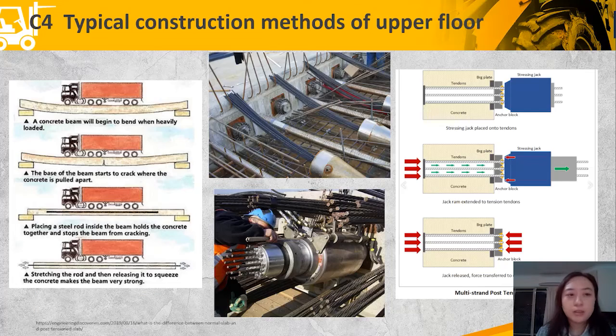When the concrete bears the load, the bottom of the concrete may crack, so post-tensioned concrete is a good way to solve the issue. It is formed by using tendons. Tendons consist of strands coated with a protective coating and sealed inside ducts.